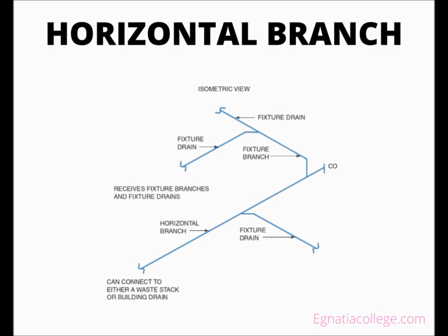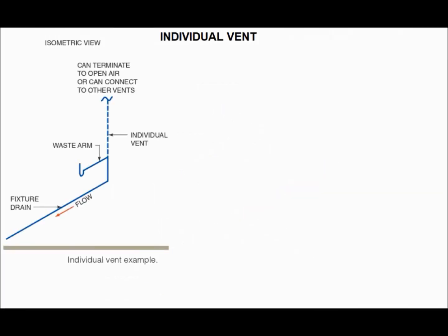Special regulations must be followed for a battery-vented horizontal branch. Typically, it can serve only 50% of the drainage load of a standard horizontal branch. It must be served with a full-size cleanout, but some codes allow a pipe greater than 4 inches to be served with a 4-inch cleanout. Because it is a drain, it must have adequate slope, dictated by codes and its size. Battery venting designs are more relevant in commercial design than residential.